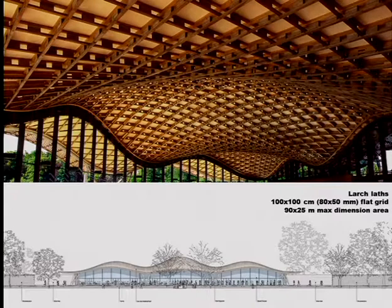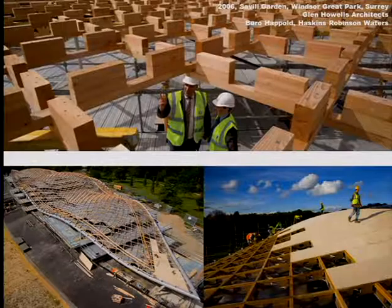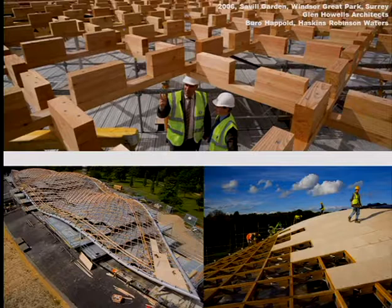Savill grid shell is the third example and the third and last construction technique so far. The way they've done it, this was very, very thick, so they couldn't bend it on site. What they did, they did 2 layers, and then they bent it, and then they built the other 2 layers on top of it. What you see here are shear blocks, and there is no bracing yet. So you see 1 layer of laths, and the orthogonal one here, with the shear blocks on top, and then they built the 3rd and the 4th layer on site, and then cladding.